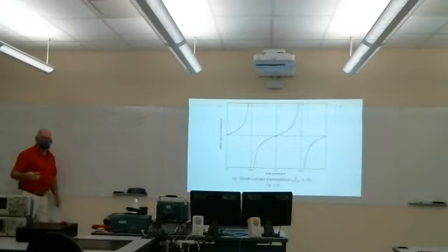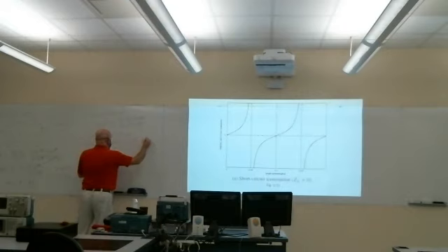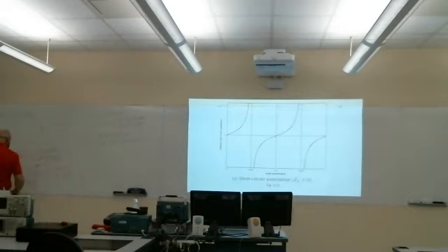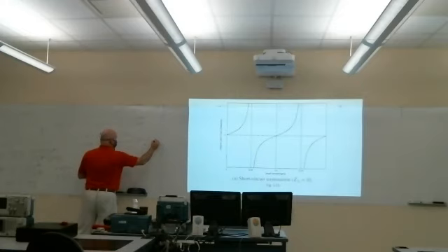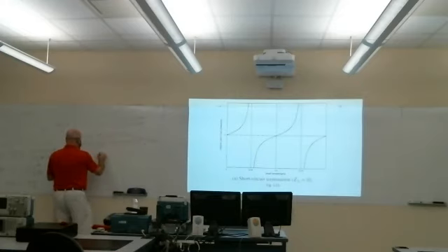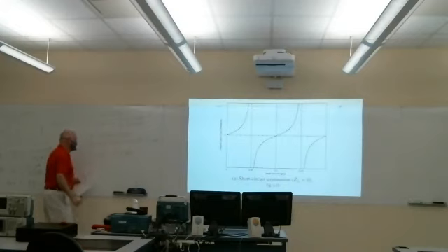So when is a short not a short? When it's a transmission line, or at high frequencies, where it may look like an inductor or capacitor. So in this case, with the short circuit, ZL is 0, so gamma is minus Z0 over plus Z0, or just minus 1. And our expression for Zin of L reduces to plus j Z0 tangent of beta L.